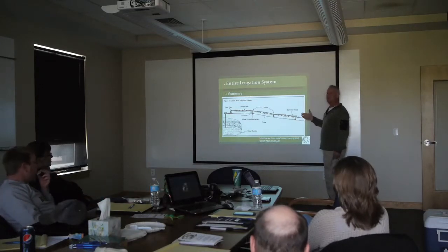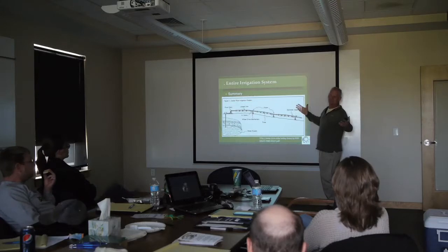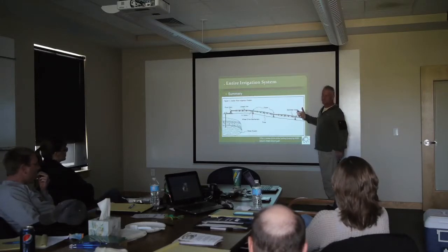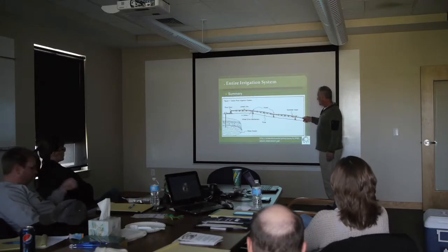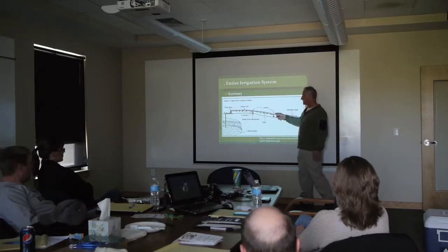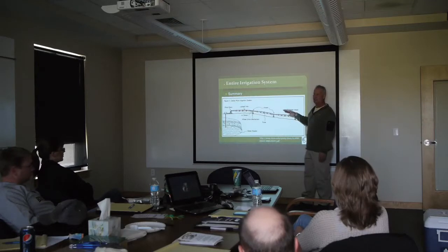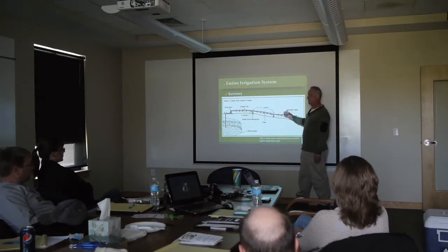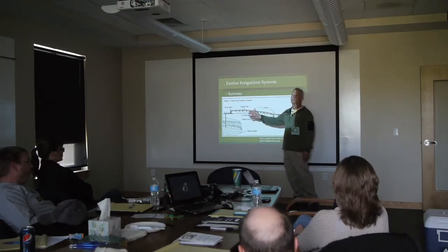Say you've got a 40 PSI sprinkler. That's typical in a low pressure system. So as long as you've got 40 PSI here, you're golden. In a system that has elevation change, you definitely would have regulators in it to make sure that they're 40 PSI all the way along.